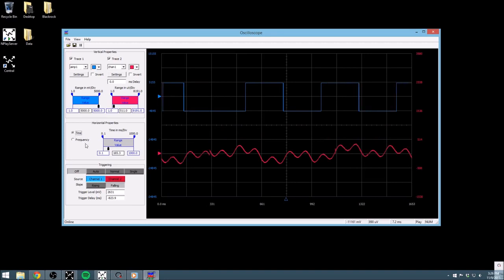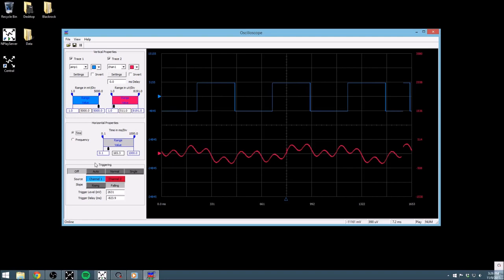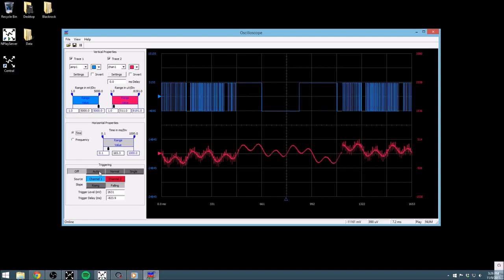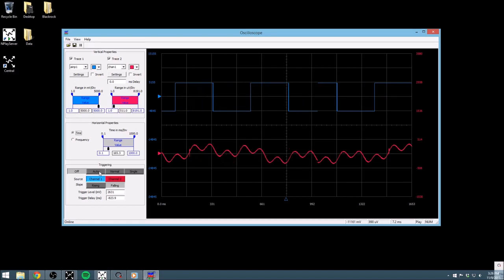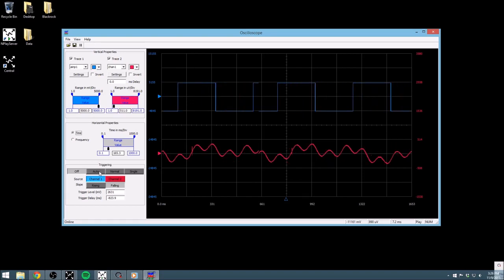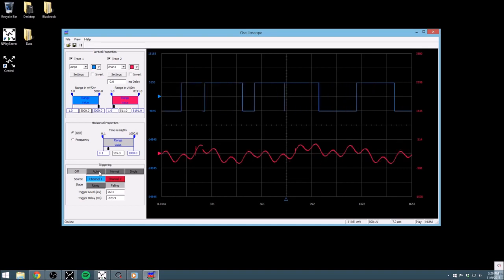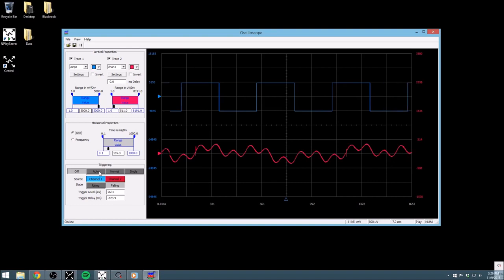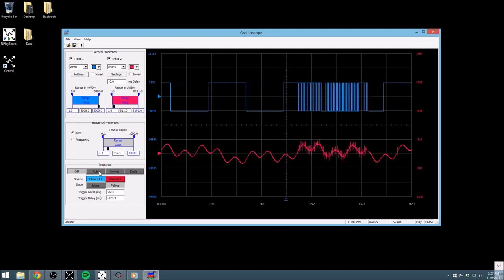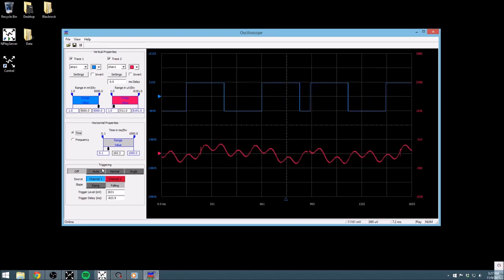If we go back to the standard trace by selecting time, we can see another common use of the oscilloscope, the triggering feature. Triggering allows us to focus on a piece of our signal based on a threshold crossing. A very common setup for triggering feature is to use a pulse on the analog inputs as the trigger to observe what happens to a given neural channel shortly after some sort of stimulus presentation. I'm just using sample data, but we can still use it to show the usefulness of the trigger features.